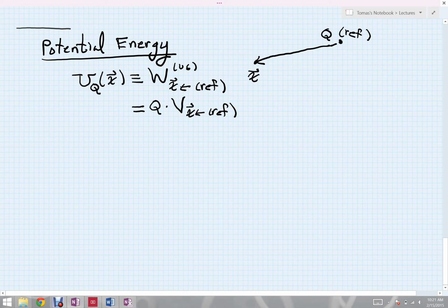Now this function here is kind of an interesting function. It's voltage, as we've been working with it, but what's interesting about it is that because we're going to agree upon some conventional starting point, what we're left with really is just a function of position x. Let's think about this for a moment. Suppose I were to actually measure this with a voltmeter. So I'll have my voltmeter here, V, and as you know, the black wire, or the minus or the ground lead, is where the starting point would be. So I'm going to always nail that lead down to that reference point. I'm not going to, for these considerations, let that negative lead move anywhere.